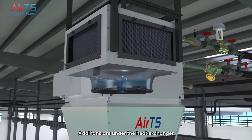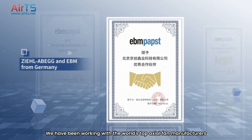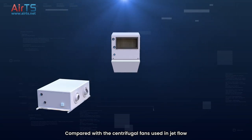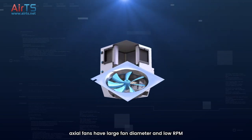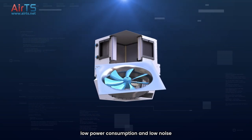Axial fans are under the heat exchanger. We have been working with the world's top axial fan manufacturers, Ziehl-Abegg and EBM from Germany, for nearly 15 years. Compared with the centrifugal fans used in jet flow type air conditioning units and modular air conditioners, axial fans have large fan diameter and low RPM, which makes them have large air volume, low power consumption, and low noise.